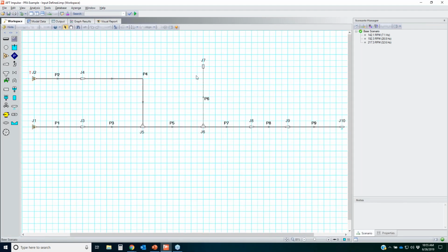So now what you would do is load each of these individual scenarios, and you're going to look at the pulsation response for each of them. Because you've already smacked the system with the hammer, now you're going to see what the response looks like when it's like the truck moving back and forth in that video, causing the buildings to shake. How much are those buildings going to shake? So that's what we're looking at here. So I'm going to double click this scenario.